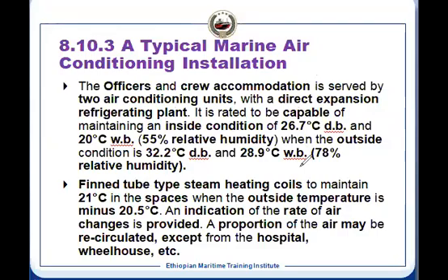we have seen in the heat exchanger chapter that whenever we have a fluid which is a bad conductor of heat, we need to design so that the heat transfer rate is high. One way we can do is increasing the heat transfer area. How we can increase? By using the fins. So fins are the extended surface on the tube.